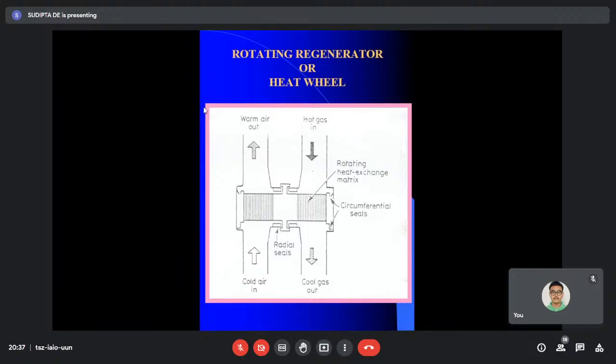More heat extracted means the hot gas must be in very close contact with the matrix. And more contact means what? The gas loaded with dust, automatically it will be deposited on the matrix surface, and that will be automatically carried to the colder gas during the heating cycle.